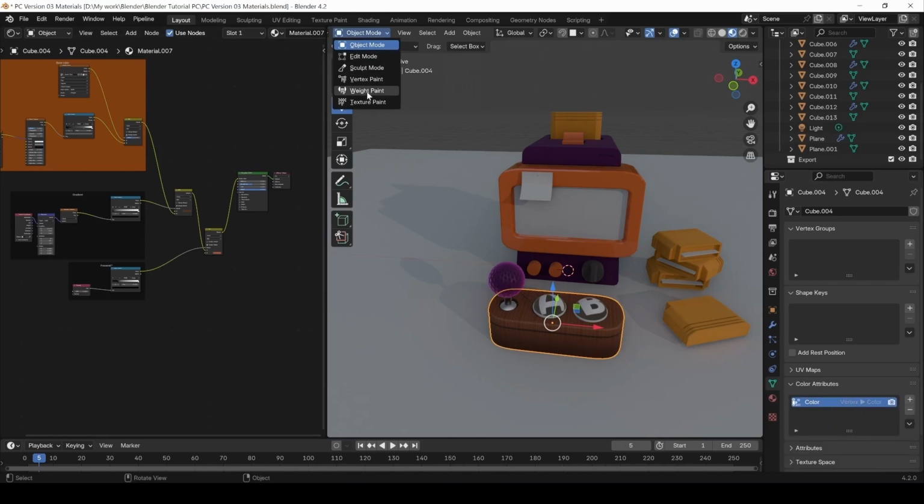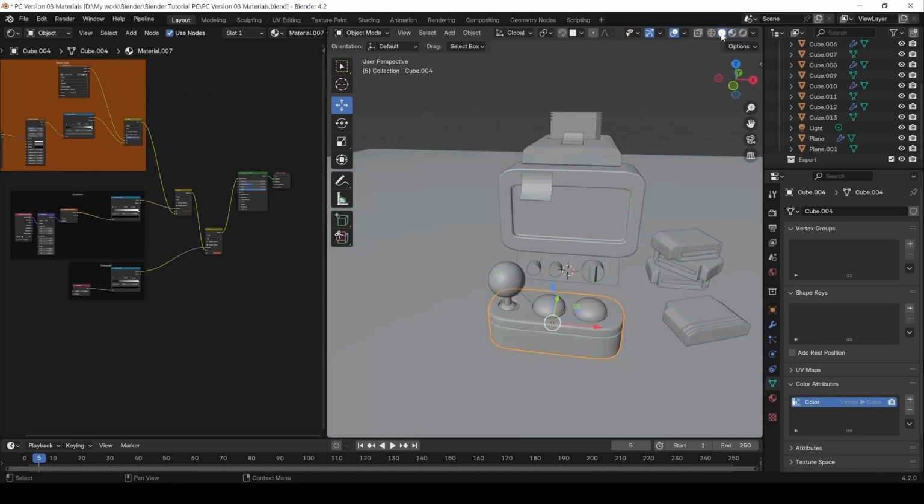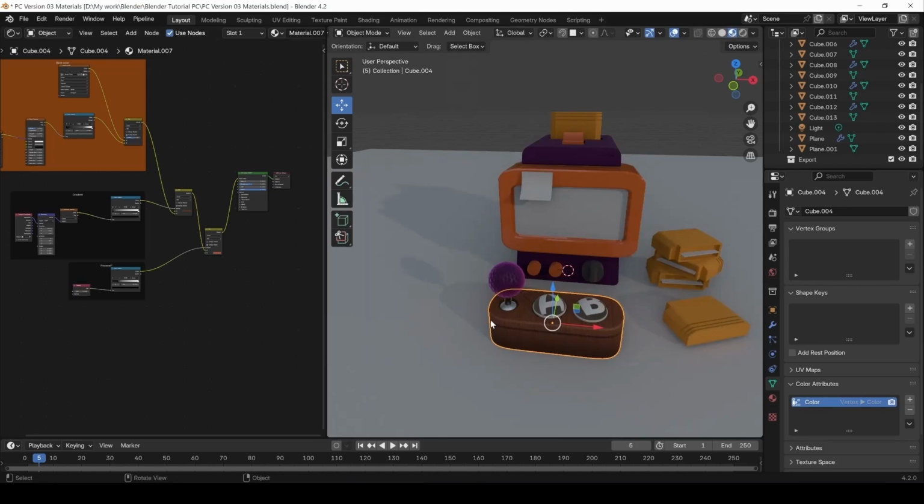Because we saw texture painting, but we actually can do vertex painting. What is vertex painting? Vertex painting is basically taking a vertex and coloring it. When you see it like that, there is no color basically, but when we color the vertex, these colors appear here because we are giving color to the vertex itself. So this can be very nice for adding some lighting effect and some shadow effect. Okay, so let's do that.